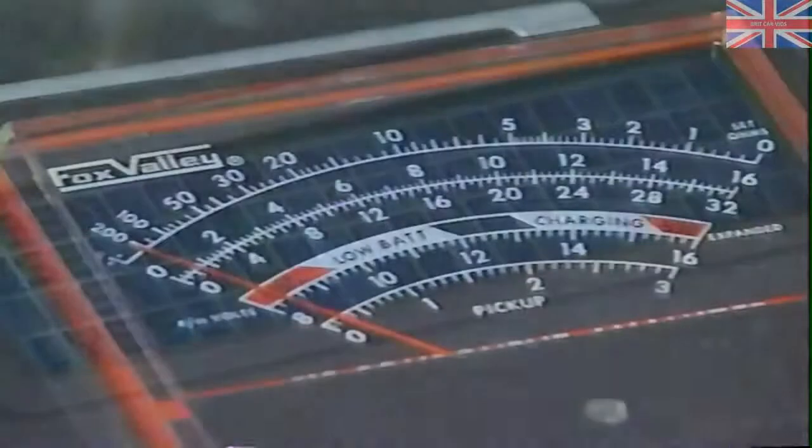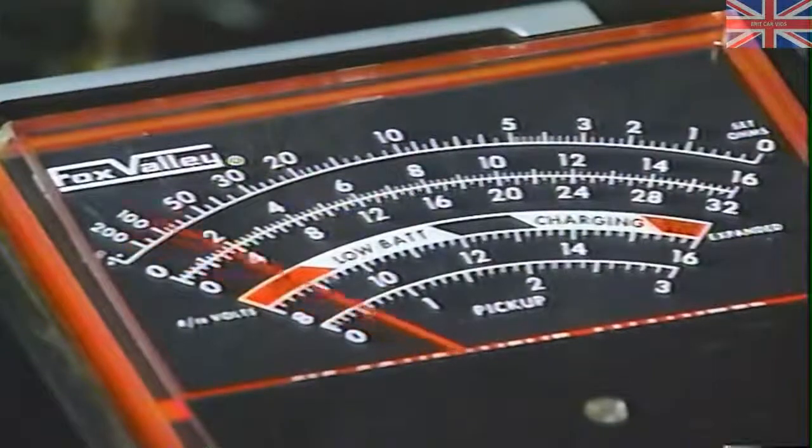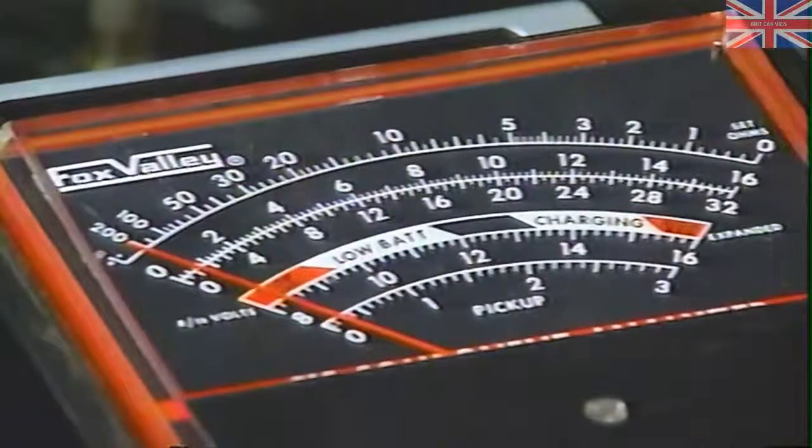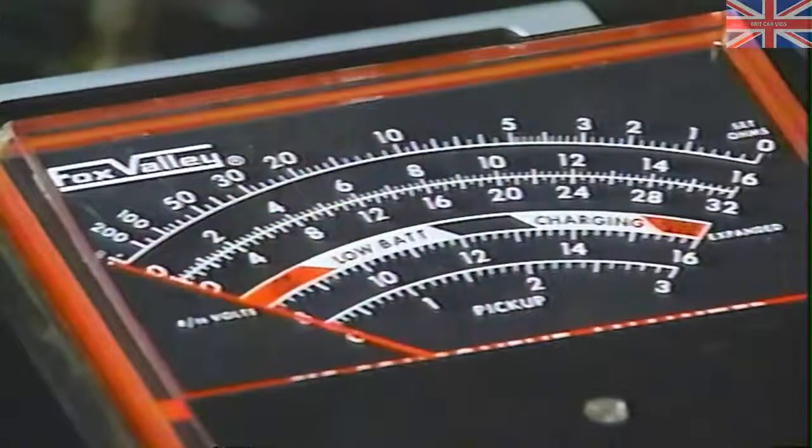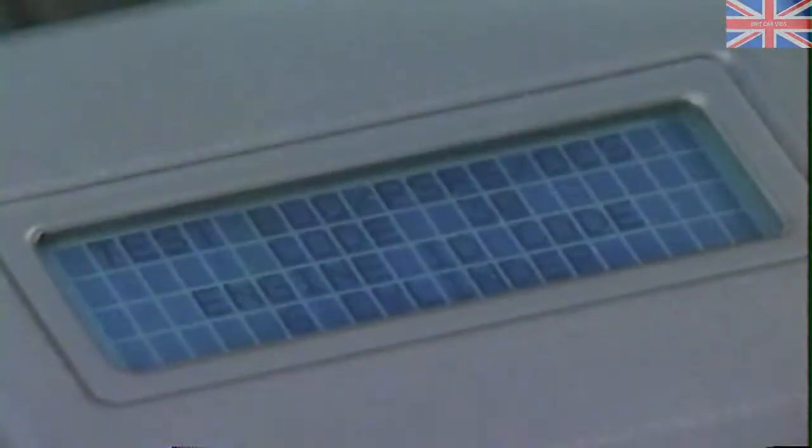The scan tool or the voltmeter will next give an indication of an engine ID code, which allows you to verify if the proper computer or processor is installed and the self-test has been entered. Engine ID code is equal to 1/2 the number of the engine cylinders. For example, 4 pulses on the voltmeter would be an 8-cylinder, or 2 pulses would be a 4-cylinder. The scan tool will indicate 20, 30, or 40. We are working on an electronic fuel-injected 3.8-liter 6-cylinder.